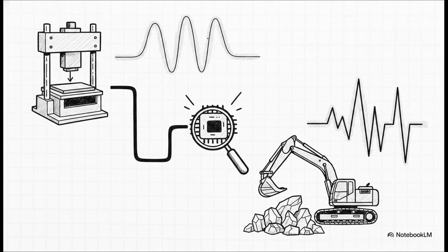Now, this sensorless detection is perfect for machines with consistent loads, like a hydraulic press. However, it's a lot more challenging for stochastic, unpredictable loads like an excavator, where random external forces can actually mimic the signal changes of a real leak.